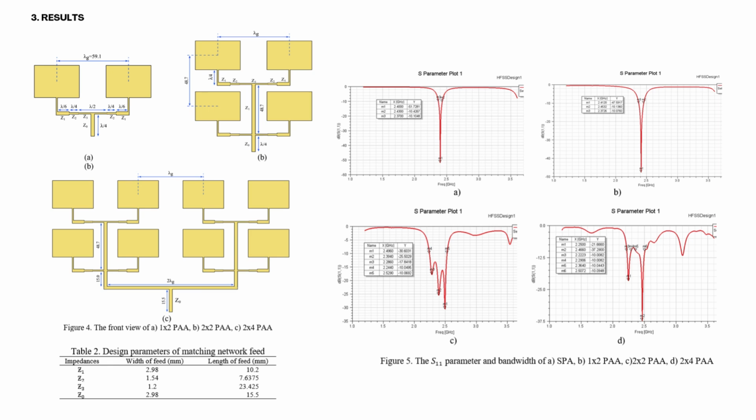In order to improve the characteristics of the antenna array, the distance between the two upper and lower antennas should be made less than the wavelength. In this case, it's equal to 0.82 guided wavelengths. The radiation elements are excited using a shared feed line, ensuring uniform power distribution between them.